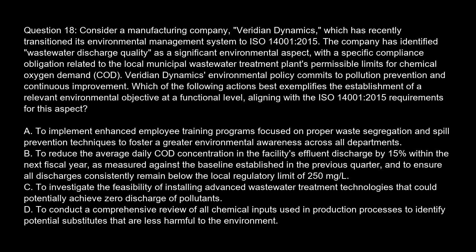Option B. To reduce the average daily COD concentration in the facility's effluent discharge by 15% within the next fiscal year, as measured against the baseline established in the previous quarter, and to ensure all discharges consistently remain below the local regulatory limit of 250 mg/L.